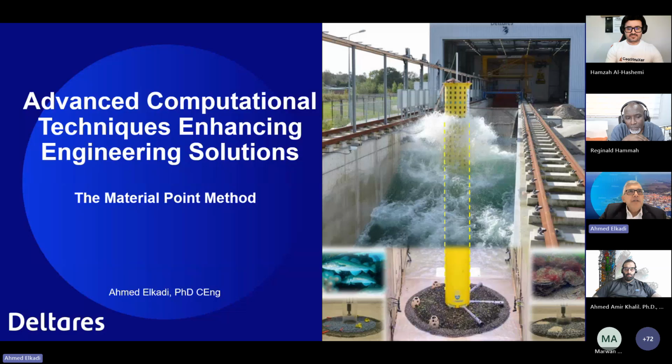On the title page, you see experimental work, and that's something I would also like to come back to during the presentation. Numerical and experimental going hand in hand. So that will also be my advice at the end, and that's why I show a bit of a complex experiment we do here at Deltares with a wave flume, where we can generate waves of 4 meters high. This is a model of a pile being impacted by waves, so the wave is impacting this offshore pile, and we can look at scour and a scour mitigation measure, just to keep in mind.